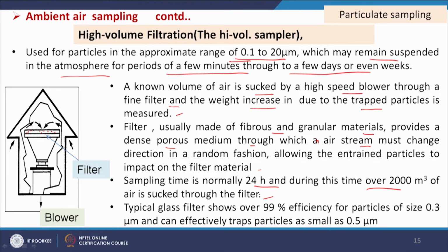So, a relatively large amount of air is sucked because the collection will be sufficient for analysis, and a typical glass filter shows over 99% efficiency for particles of size 0.3 micrometer and can effectively trap particles as small as 0.5 micrometer.